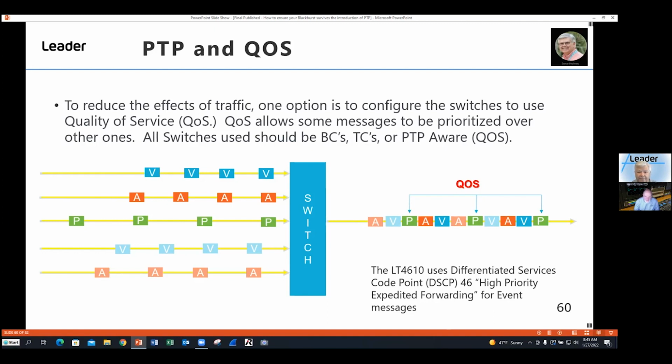So, Steve, SMPTE 2110 standard specifies real-time RTP-based transport of uncompressed active video essence over IP networks. So if my understanding is correct, unlike SDI video, 2110-20 results in both a vertical and horizontal phase offset?